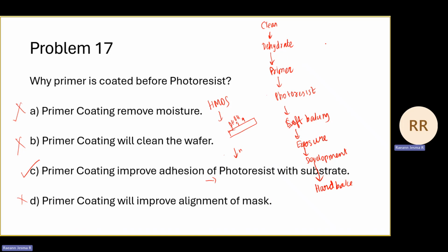So let's say you want, and why do we want to reduce the thickness of the photoresist? The thickness of the photoresist will affect the resolution of the pattern that we are writing. So resolution is the smallest feature that we can write, and it's generally measured as critical dimension. It is also referred to as critical dimension. If we have a thinner photoresist, then we'll have smaller resolution.